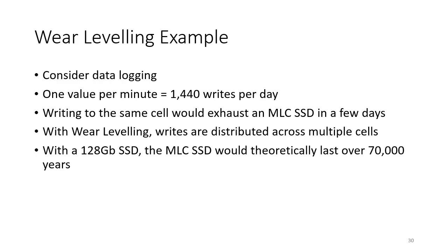only. With wear leveling, you now write across multiple cells, and those writes are distributed by the controller. So instead of lasting only a few days, if you had a 128 gigabyte MLC SSD, that would now theoretically last over 70,000 years at the same write level. That's how wear leveling can be used to considerably extend the life of the SSD, because instead of writing to the same cell, you're writing to multiple cells, not all at the same time, one after another at different locations, and that considerably extends the life of the SSD cells.